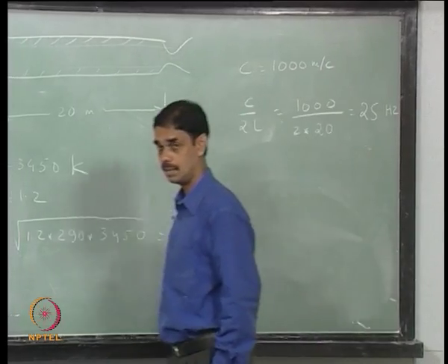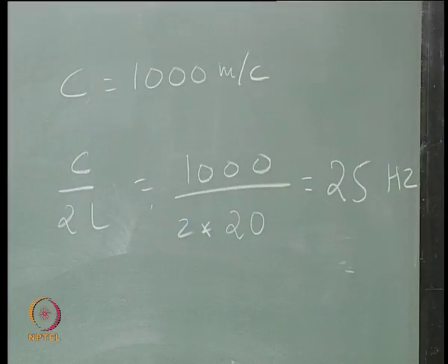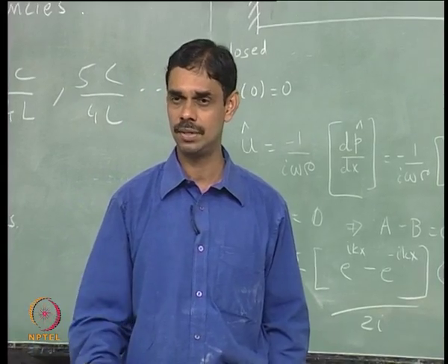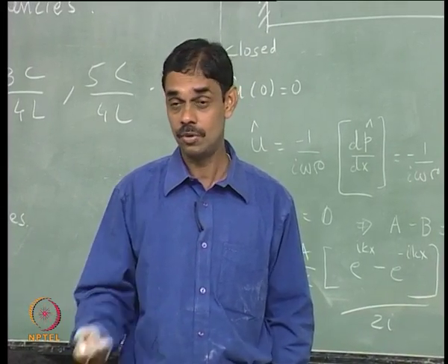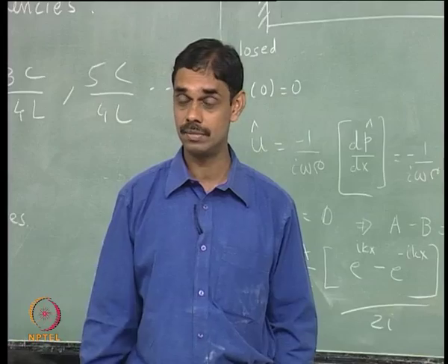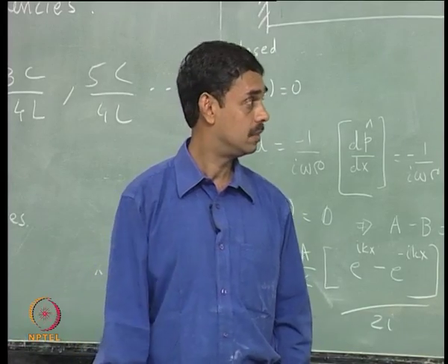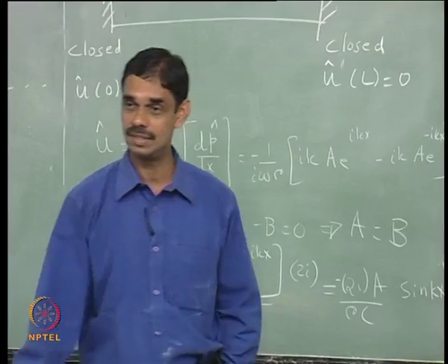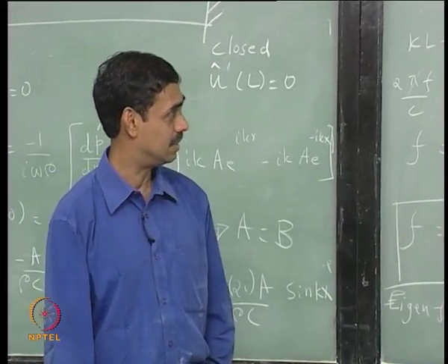The actual motor is a fairly stable motor. Any motor will have some level of oscillations, but this motor has been working very nicely. But they put pressure transducers and found that the amplitude is very small, but you still see natural frequency in terms of small oscillations. The frequency is of the order of 28 hertz, so we are pretty close with our really crude calculation.